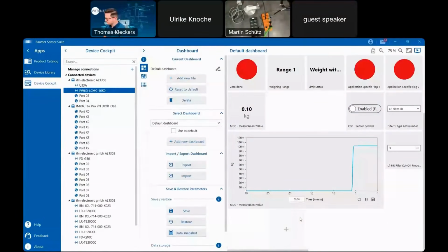Now, the important thing is once you have the IODD file and do the setup, it is possible to do all your settings, to do a copy of all your settings in the master. And in case you need to change the sensor, just plug the next one, the measurement goes on. It's really true. And what you have also, which we wanted to show you, it doesn't really matter if you connect a force sensor or a load cell. The doing is always the same.